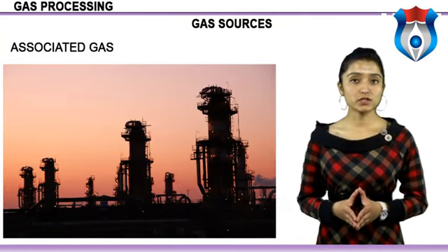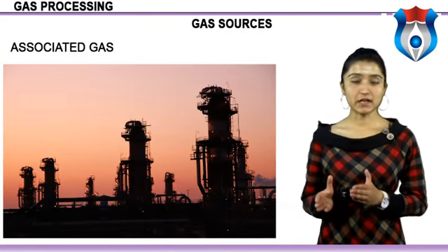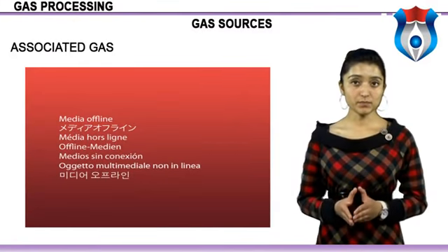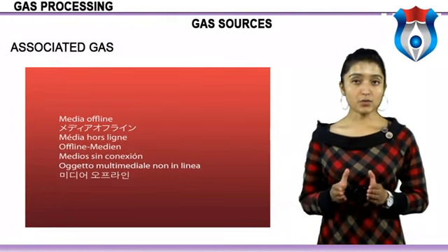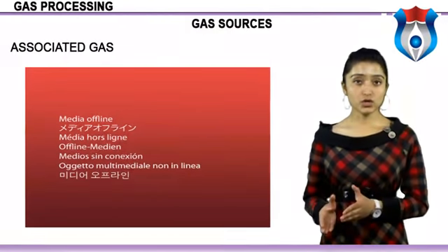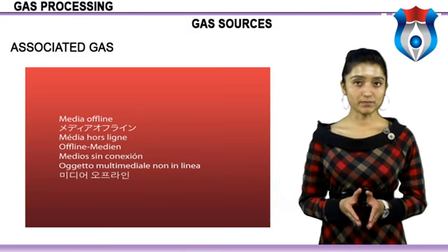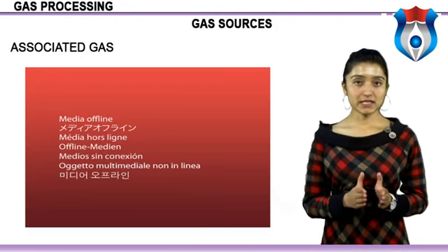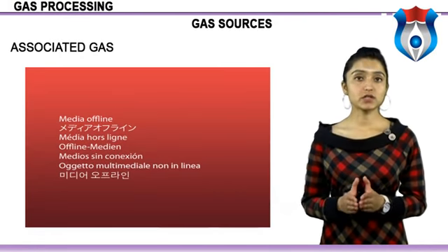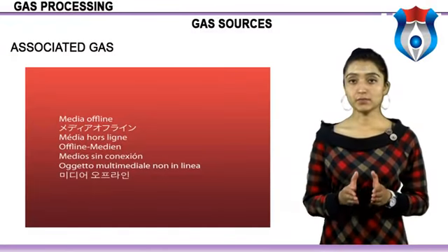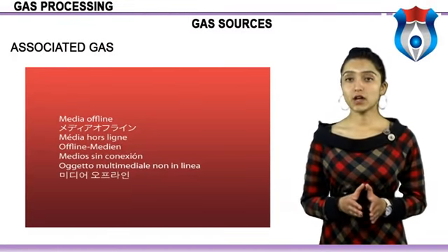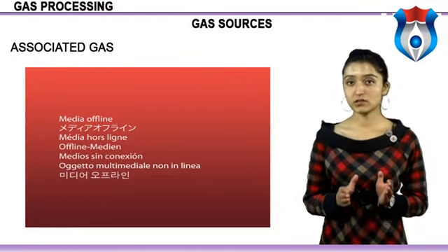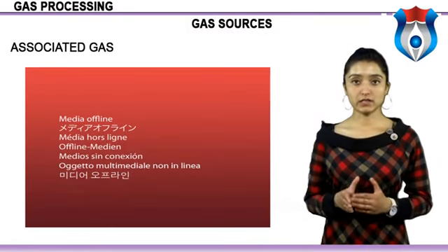After the production fluids are brought to the surface, they are separated at a tank battery at or near the production lease into a hydrocarbon liquid stream, crude oil or gas condensate, a produced water stream, brine or salty water, and a gaseous stream. The gaseous stream is traditionally very rich gas in natural gas liquids, NGLs. Natural gas liquids include ethane, propane, butanes, and pentanes, and higher molecular weight hydrocarbons, C6+. The higher molecular weight hydrocarbons product is commonly referred to as natural gasoline.